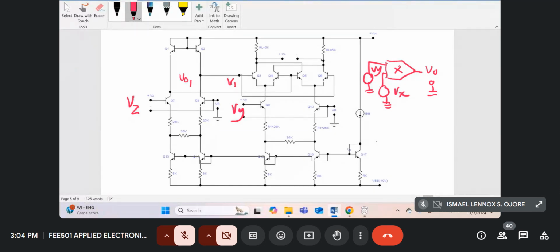We'll analyze this circuit, which comprises Q7, Q8, which is referred to as the predistortion circuit or preconditioning circuit, and see how it extends the dynamic range of the signal V1, which was input to the basic Gilbert multiplier cell, to approximately plus minus 10 volts. So it's approximately equal to the dynamic range of the signal Vy in this circuit. So I'll stop over there.